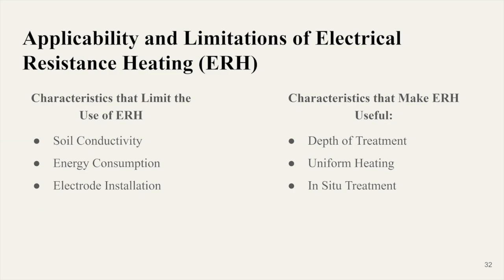Now we go on to electrical resistance heating. Electrical resistance heating has very similar applications and limitations to TCH, starting with characteristics that limit the use of the method. Soil conductivity, since ERH may be less effective in soils with high electrical conductivity, as it relies on the passage of electrical currents through the soil to generate heat. In such cases, additional amendments may be required to enhance conductivity and improve treatment efficiency.